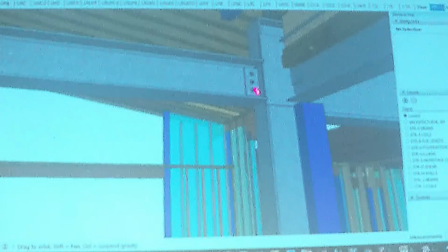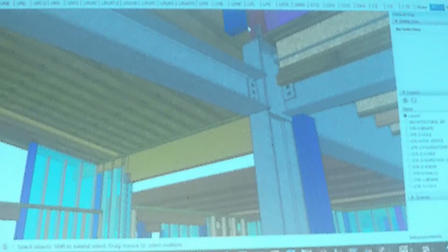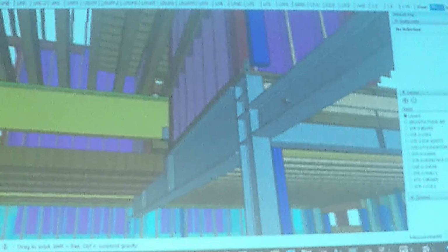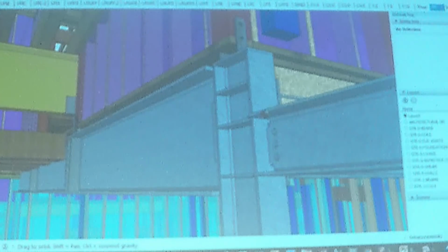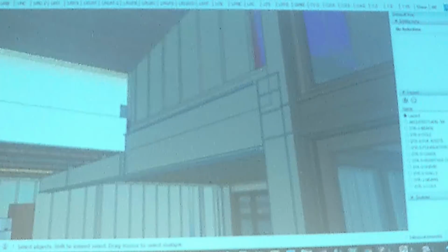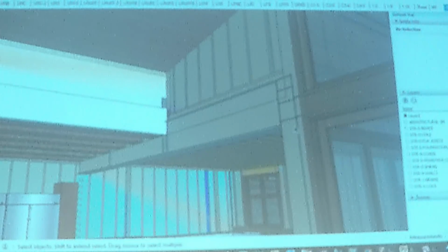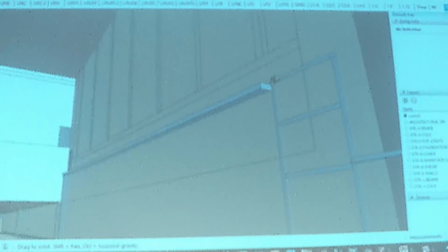Okay. Yeah, we've got all the connections in here, all the coves for welding, all the stiffener plates, all the ears for posts coming down to it. Everything is in the model and is also referenced out for the steel shops. So once this goes to Nick, Nick takes a look at this and says, wait, that's sticking out 1 5/8", and he can make a decision what to do or direct us what he wants to do.